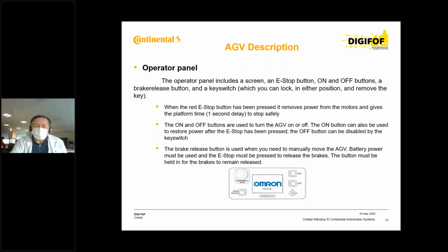With this operator panel, you can see the task that the AGV is doing. You can release the brakes in case the AGV is blocked, so you can manually push it until we reach the standard position, and then you can reinsert it into the fleet.